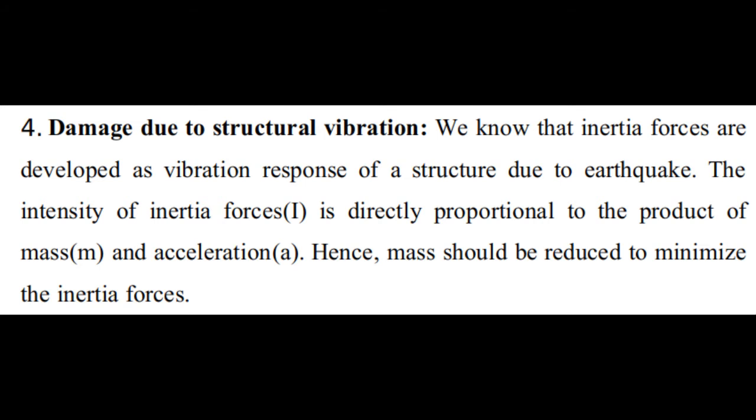Let me explain this point further. As you know, what is inertia force? Inertia force I is equal to m into a. This concept we get from Newton's second law, correct? So due to the earthquake, as a vibration response, these inertia forces are developed. We have to take care of the intensity of these forces. How can we take care? As I is equal to m into a, mass should be reduced. If the mass is reduced, the inertia forces will also be reduced, correct? So that will cause less damage to the structure. So let us see how we can do it.